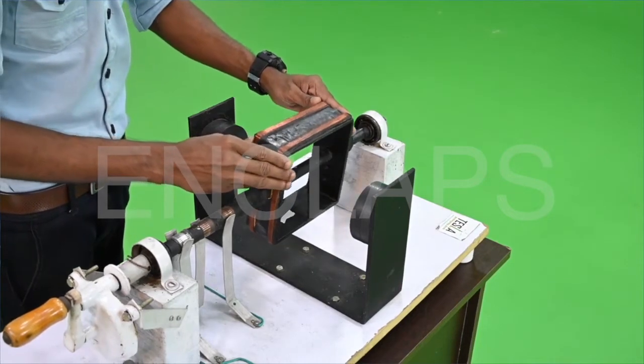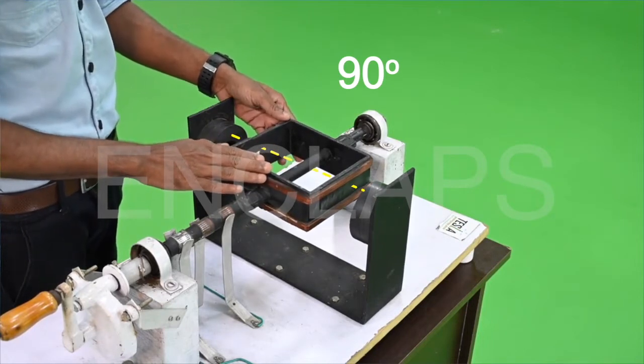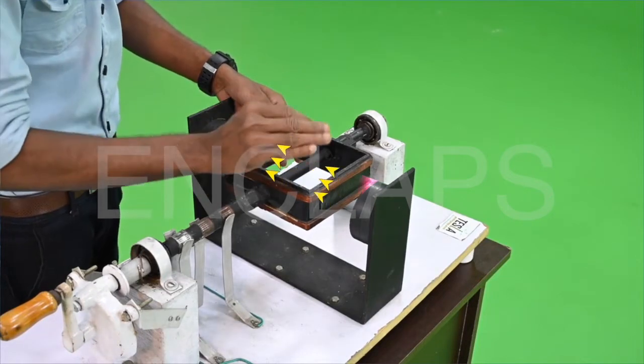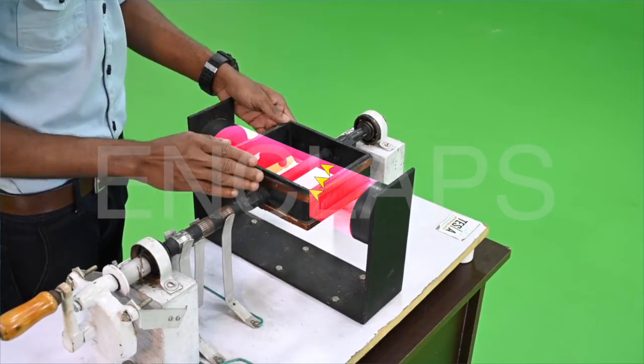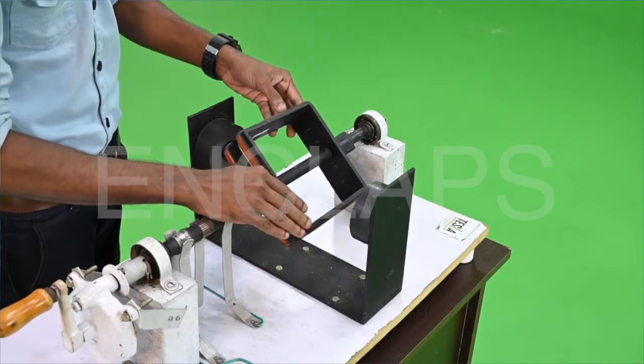After a 90-degree rotation, the armature coil aligns at this position. Here, the magnetic field lines and the armature coil align in a perpendicular direction. That is, armature is cutting maximum field lines. So, the change in magnetic flux will be maximum and hence the induced EMF and the current will also be maximum. CD is now facing the north pole and it is rotating downwards. So, a current is induced in the respective direction and the direction is said to be positive.